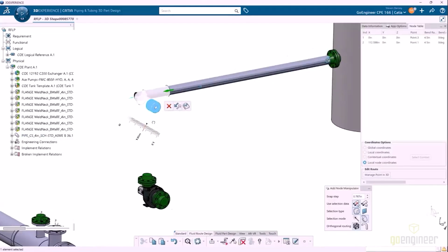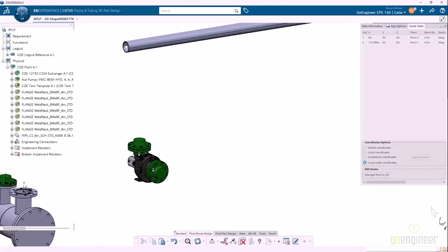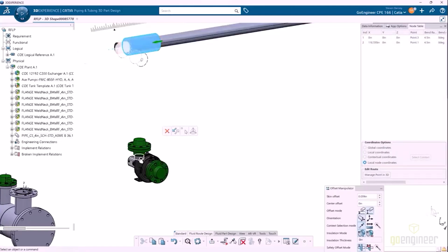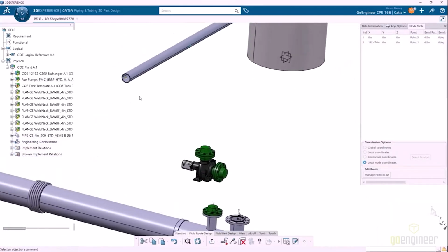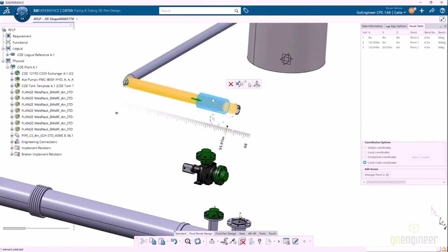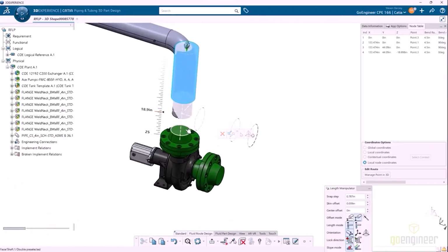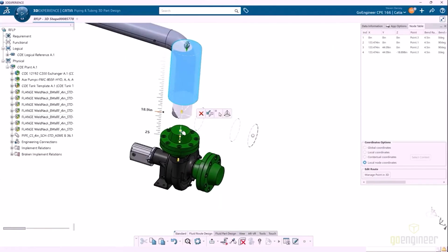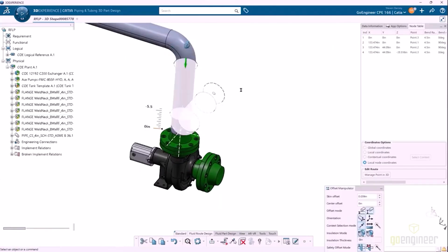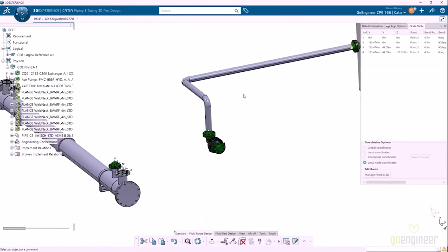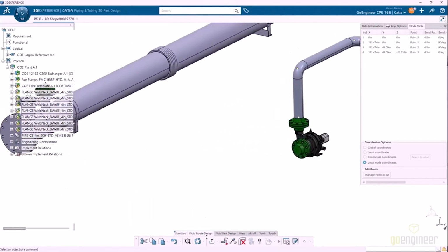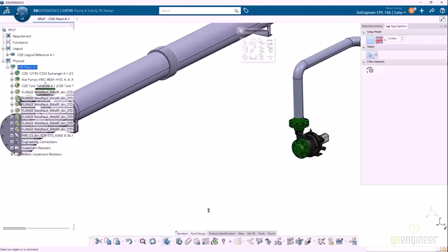And then we just drag that out. Now, the cool thing is when I pre-select that, I can select on a cylindrical face and it'll automatically align that. So to do the same thing, pick on that blue, pick on the cylindrical face, and then it's aligned. So this one I need to drag on down, and I actually have the port that I want it to stop at. So I just pick on that and then pick out in the middle of nowhere, and now it's aligned exactly where it should be. All right, so we'll exit out of that route.